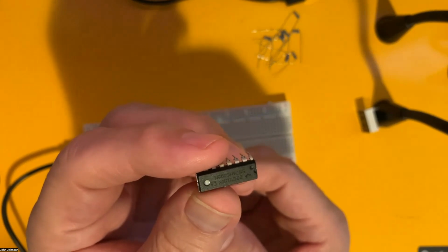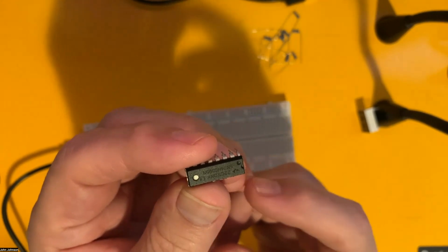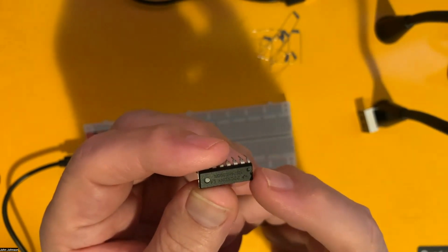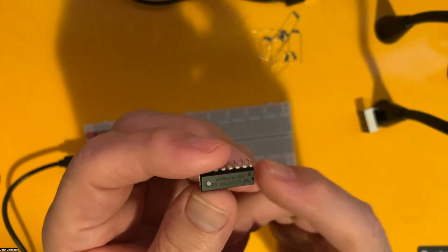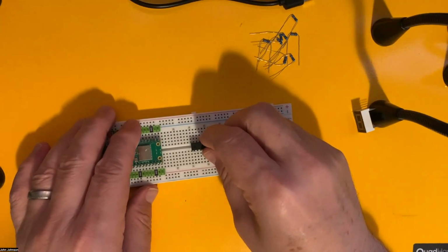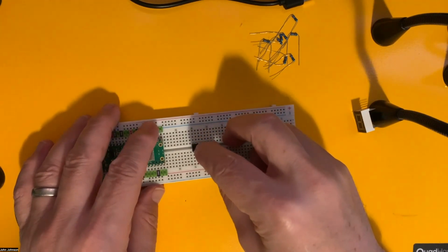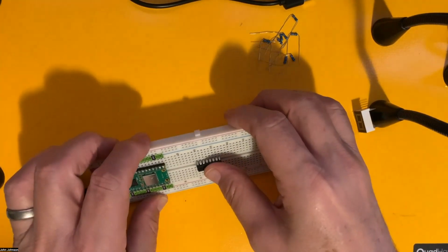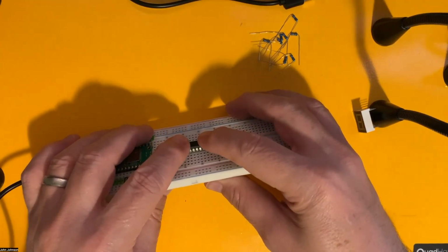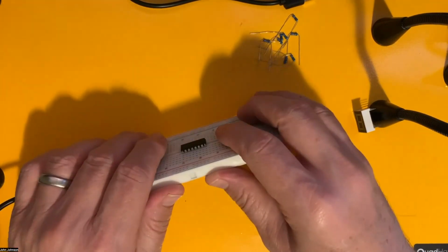After you're done putting these in, check and make sure that you have them aligned properly again. We're going to make sure that we have our writing upside down, which we do now. The little indent on the chip is right there, so this is the orientation that we want. We're going to move it over here and put it into the first one. Let's make sure that we're in the holes. Yep, we're in the holes. We push down nice and firm, and it just sits right in there, and we've got it.